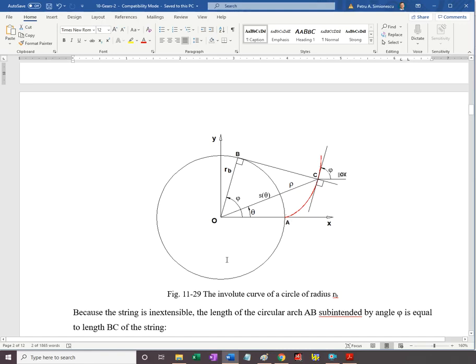And now hold the can fixed, and let's assume that the wrap extends enough around. I think I started saying that this is where the glue ends. Let's assume the glue ends past point B. Anyway, so I have the string fully wrapped, and I unwrap it by holding the string taut, and I'm marking on paper, which is fixed with the base circle, this curve in red, and this is the involute of the given circle.